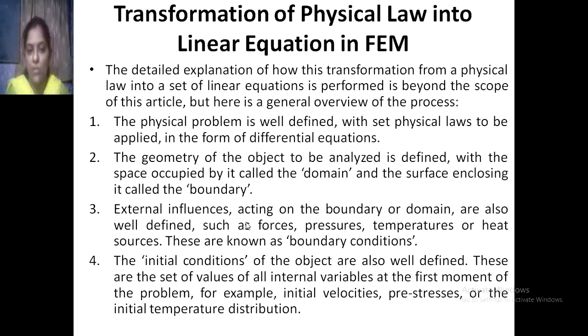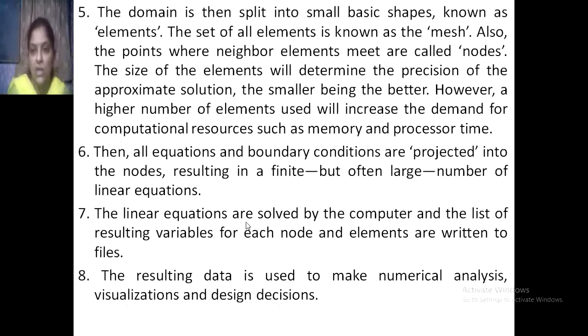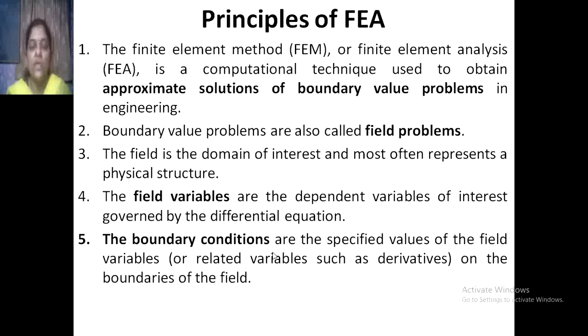A physical problem with a set of physical laws, then the geometry of the object, which is the domain or boundary. Then the external influences on the boundary, as well as the initial conditions, then how the domain is split into a number of elements, and how the linear equations are formed. That we have already seen. So in today's session we are going to see the principles of finite element applications.